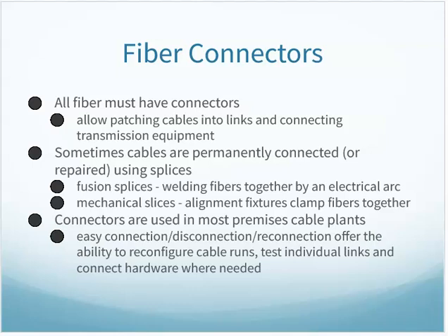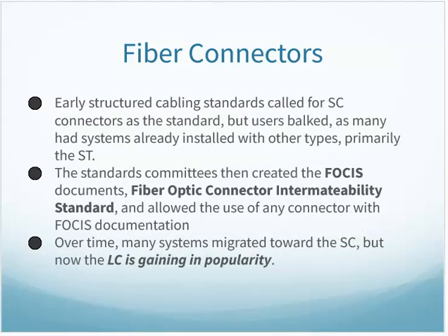Fiber connectors. All fibers need some kind of connection. Eventually, I can pull fiber and then terminate, or I can actually have it terminated and pull it. That's something that can also be done. But my terminations can be done a couple different ways. We can fusion splice them together, or using a mechanical splice, I can splice them together. And the connectors themselves, old school would be epoxy on, modern would be fuse the connector on, which would be the style we use later this semester.